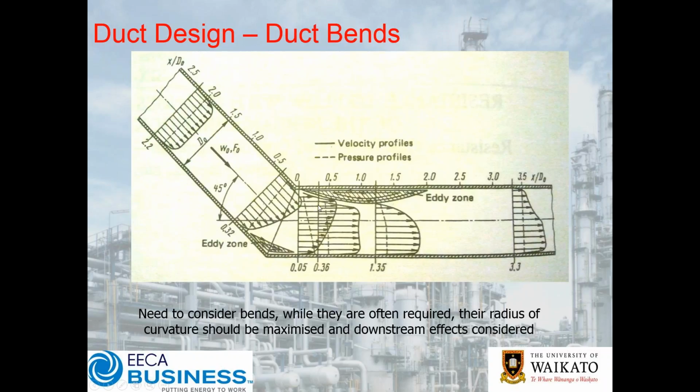So your airflow's coming down a duct, you've got a mitered bend, fairly stock standard. You see this sort of duct transition up and down the country all over the place. And what you'll see is when we hit this transition, you'll notice the airflow's coming down, down, down. And of course what's happening is 2 things. The flow's wanting to short circuit the corner obviously, but it is actually detaching. And you get this eddy zone in here.